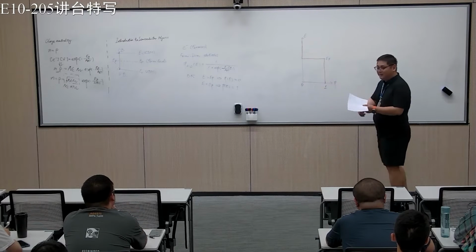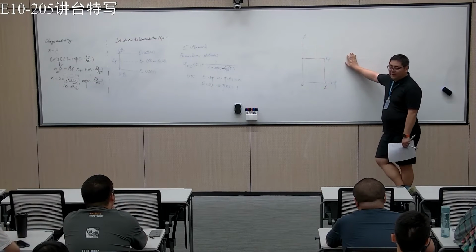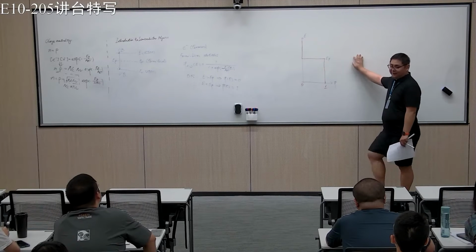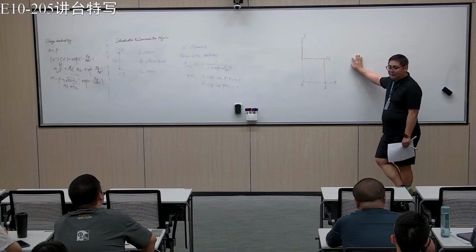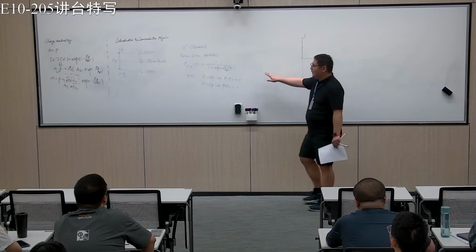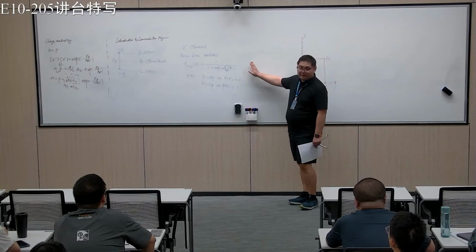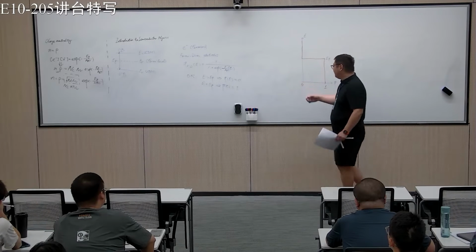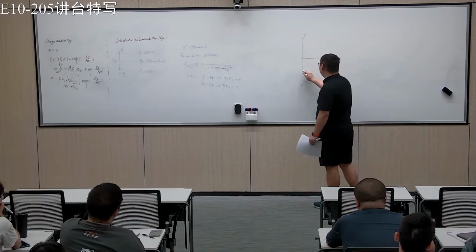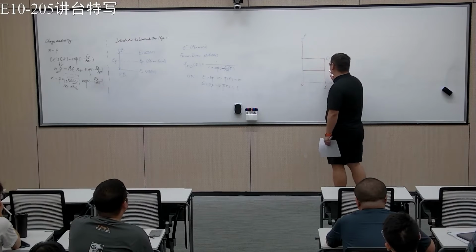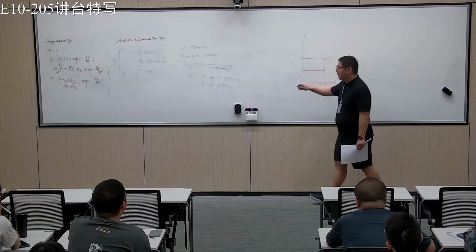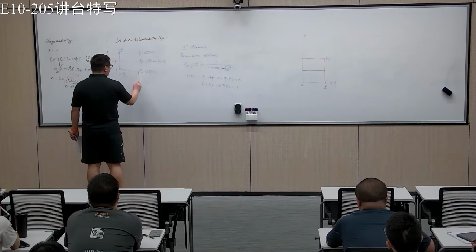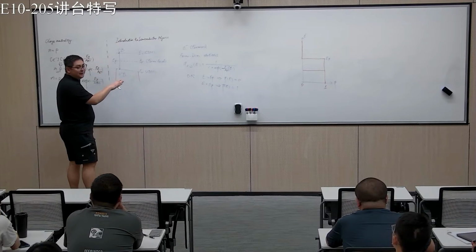Basically at 0 Kelvin, all the states below the Fermi level are occupied, if you have the state. For the Fermi-Dirac distribution, this function does not tell you how many electrons you have. It tells you whether, if you have a state, it is occupied. For example, if I have an orbital or state here, as you can imagine, in the valence band there are many states, right?